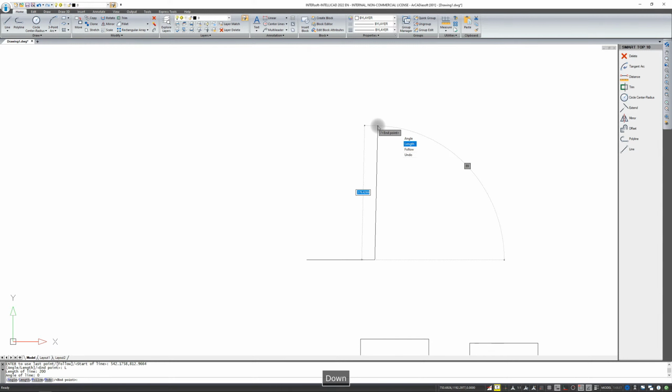I'll enter the length, that is the letter L, type in 500 and confirm with enter. Now for the angle. I will type 90. For a change, we will now choose the angle. I will enter 180 and the length will be 200. And now if I were to enter the angle, it would also be 90 degrees from the last entered value. But I'll just close it and another rectangle is drawn.